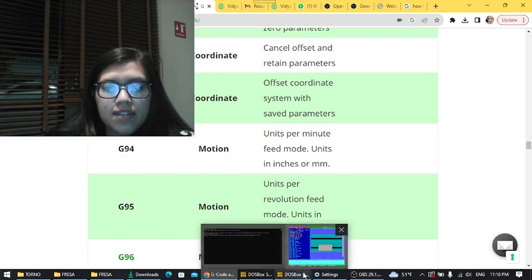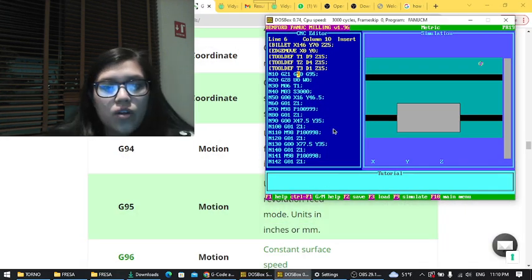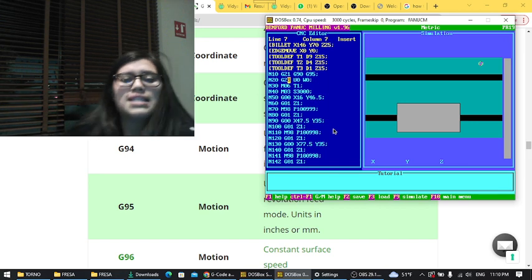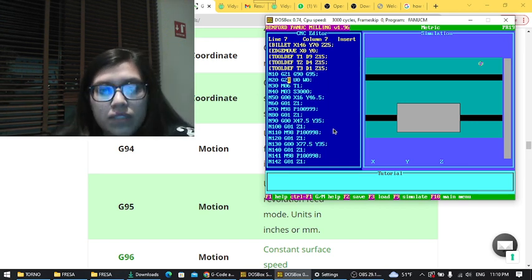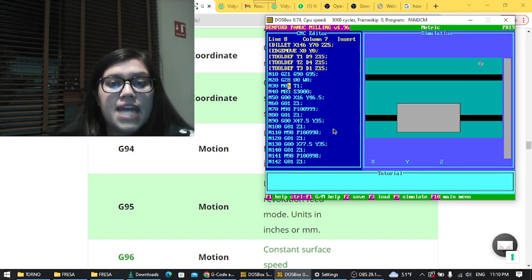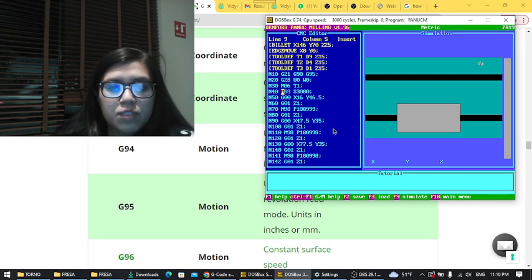Now, after that, we're going to see what G28 is. Basically, this is just securing the home position. After that, we have the M codes. I have established that they're basically just like commands. In this first one, it's commanding that we bring in tool number 1, as we can see here. And M03 is establishing the start of the spindle. So it's just that.